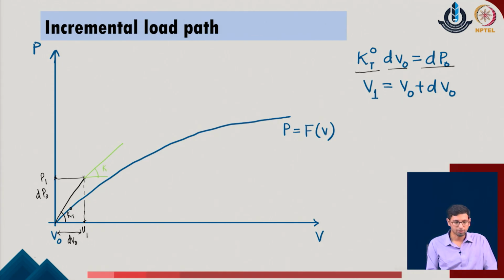So, I will come up with the KT1, which will be evaluated as KT with respect to V equal to V1 in the given problem, and again we give a second level of increment in the given system, which could be defined as dP1. With this increment, we reach the new position, which is P2, and corresponding to this P2, we obtain the displacement. This happens to be the second displacement, which we call V2, and this is the increment identified as dV1 in the given system.